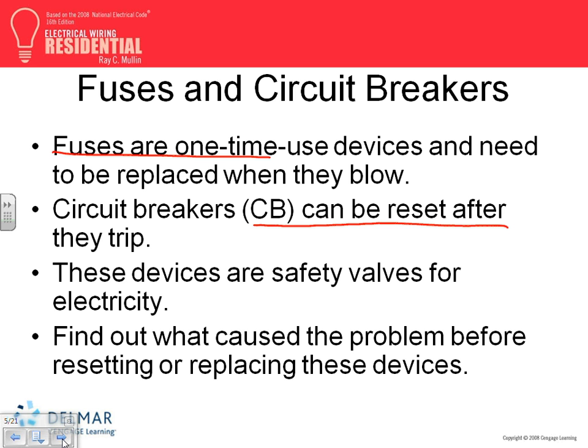So now you can have a 10,000 amp transformer hooked up to a system where the available short circuit current is 20,000. Why? Because I have these filters, which are fuses. They call them current limiting fuses. That's a major advantage of fuses over circuit breakers. Circuit breakers don't have them. Yeah, there are some exceptions, but for the most part, they don't have them.